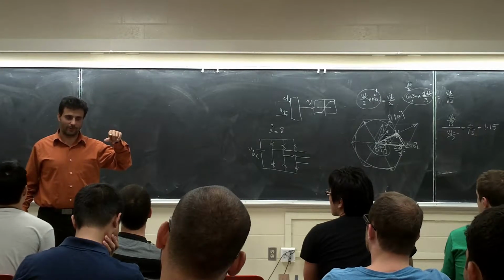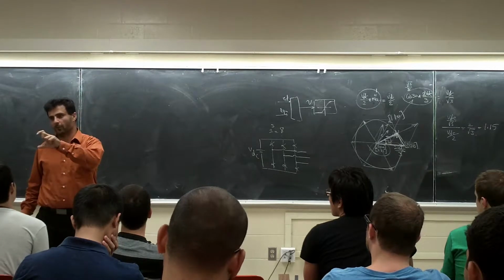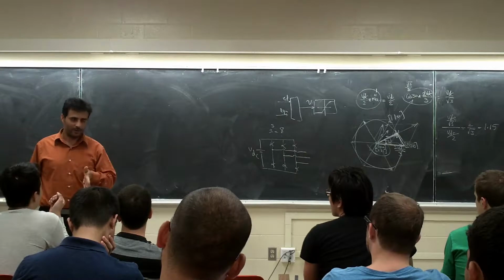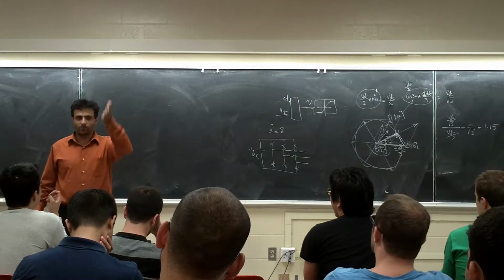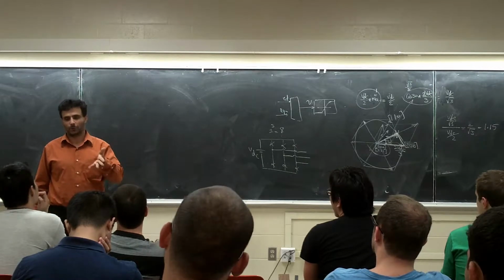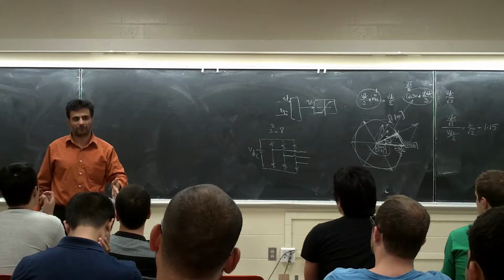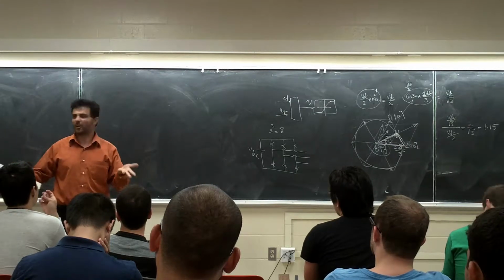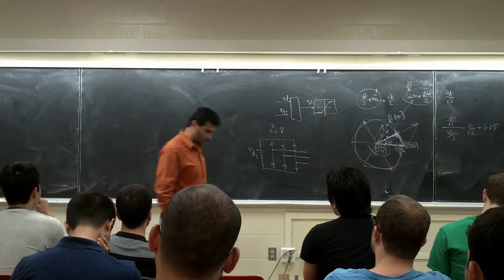I think you're going to start with a single output flyback converter, for example, 115 volt. But the next phase, in the same homework, is not homework, I think lab, I should call it something like that, is multiple output. You have seen in your lab, you have 15, minus 15, you have 5, right? And it's all in one box. There's not 3 power supplies, right? That's a flyback converter with multiple output. You go work on that one.